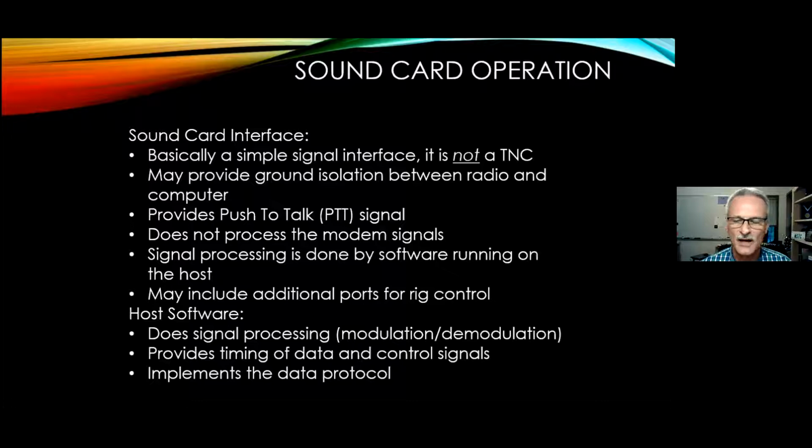A TNC does a lot more than what a sound card interface does. Some of the things, it may provide ground isolation between the radio and the computer, and I'm going to talk about whether that's necessary or even desirable anymore. It has, of course, to create the push-to-talk signal. We have to be able to put your radio into transmit mode, and that can cause us some issues sometimes, and we'll talk about that a little bit too.